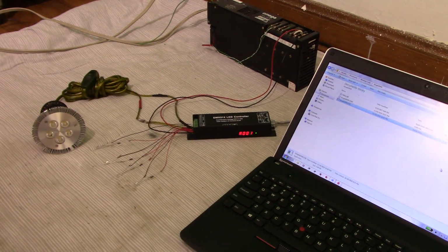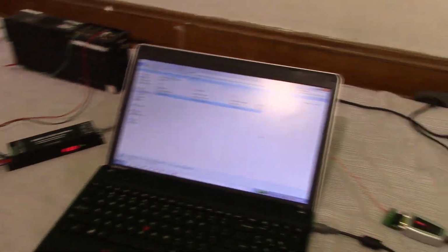You can buy DMX dimmers that run directly from alternating current. They don't have to be direct current, and normally they just plug right into the mains, and then you plug whatever mains powered lights right into them. You normally see those in concert halls, theaters, museums, and things like that. But this one's just for the demonstration. This runs LEDs. And as I said, most DMX communicates over an RS-485 network.